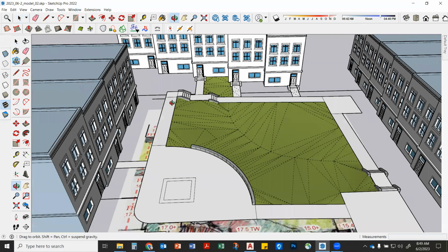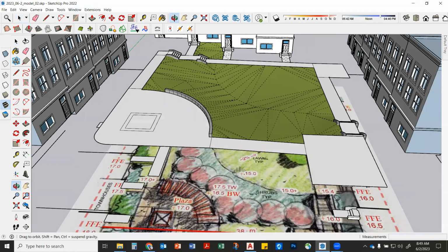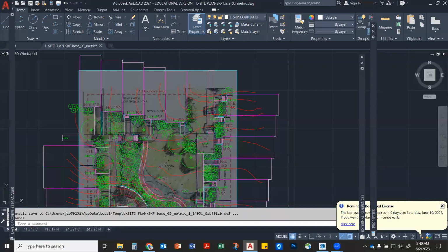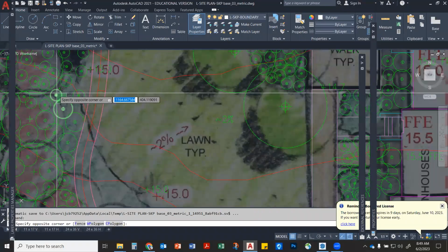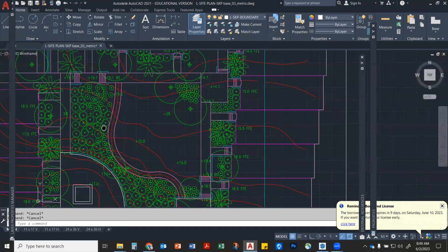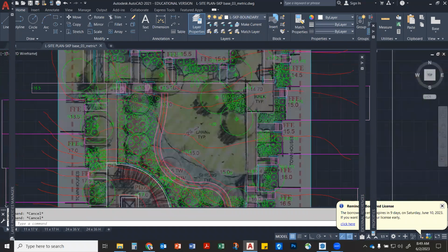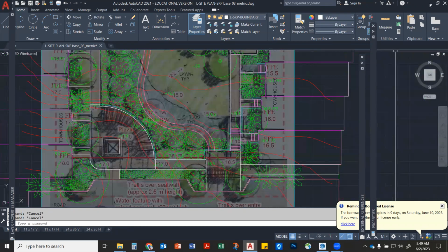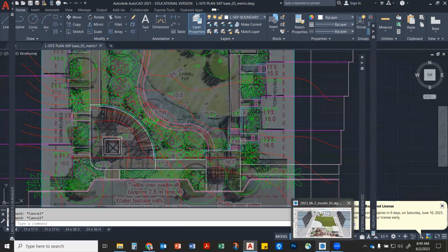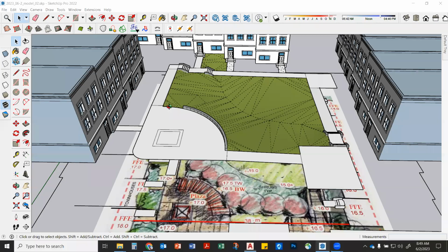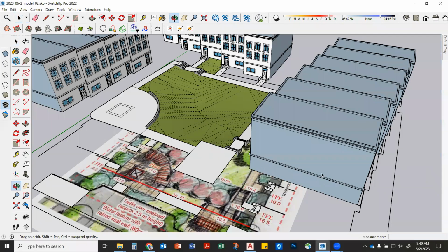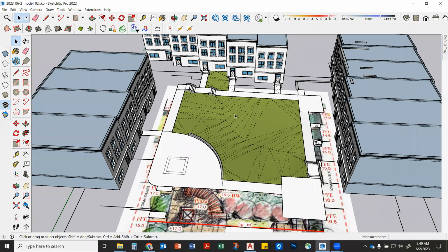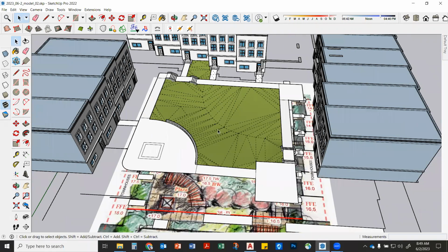So now what we can do with drop GC is bring in, remember all these plant files that I had in CAD, all these CAD blocks? We can bring all of those in and actually drop them directly into our file, and they'll drop down on the terrain if we use drop GC, okay? So what we're going to do is import it. We're going to pull the blocks above whatever tins we've made, and then we're going to drop it down, okay?